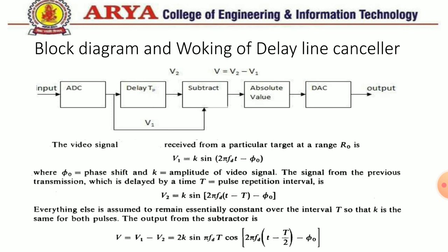We are able to eliminate the clutter received by the radar, which is an unwanted signal. Clutter is a noise signal. That is what we eliminate with this delay line canceller, and the absolute value is given to the display to identify object position as well as motion.